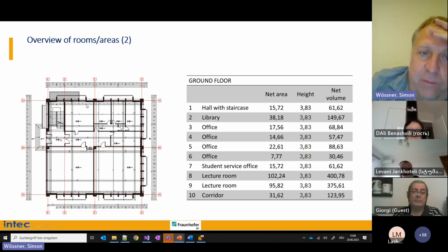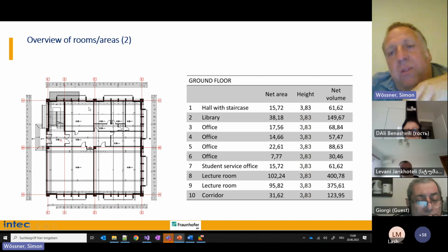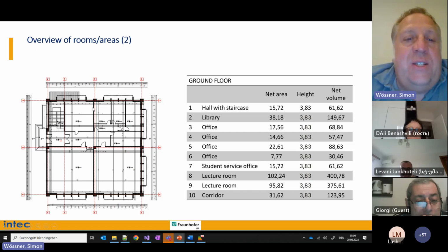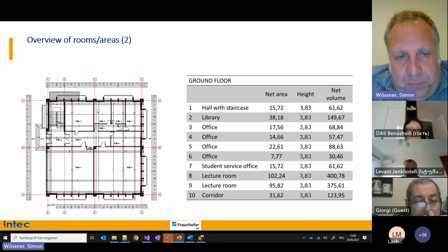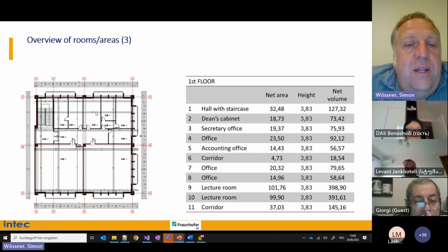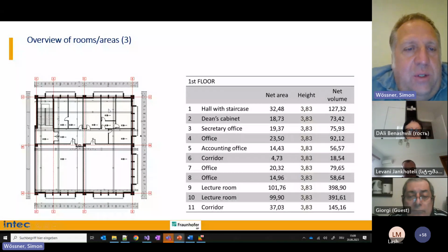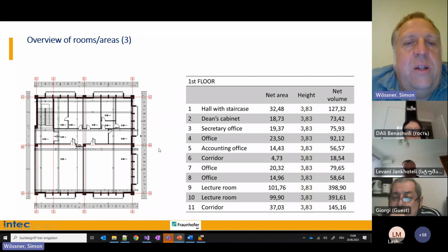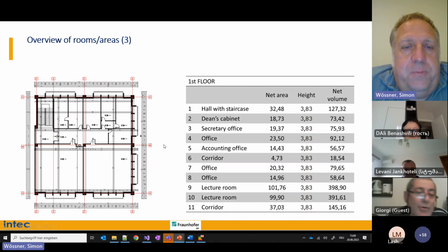actually 1.25 meters wide, which is information you can use together with a cross section to calculate the areas of the windows. And that is the first floor, again measured, and we use some of the measures also to calculate the area of the flat roof, for instance.